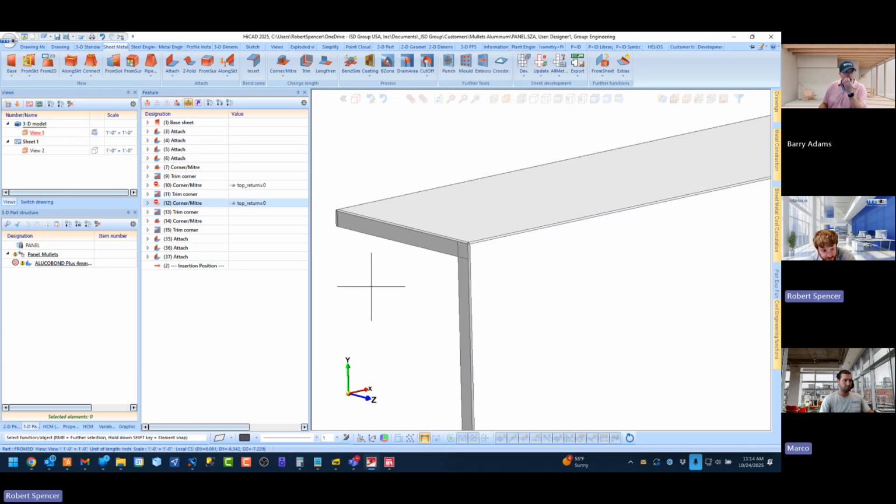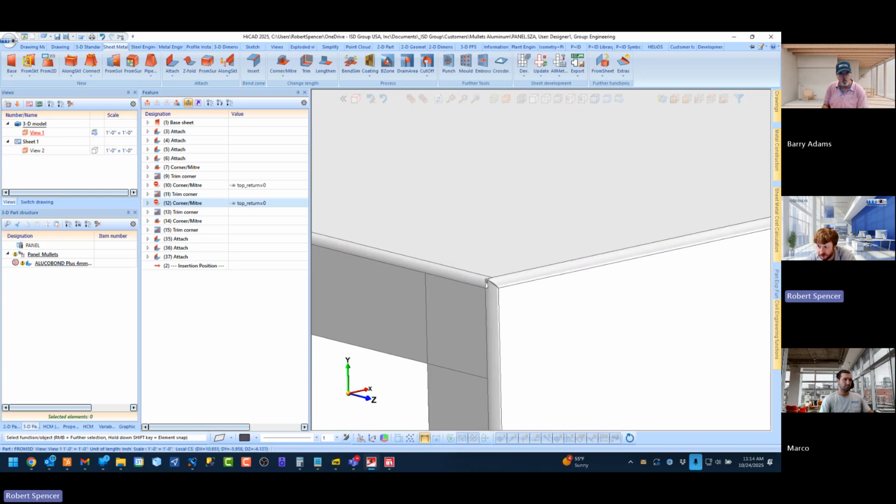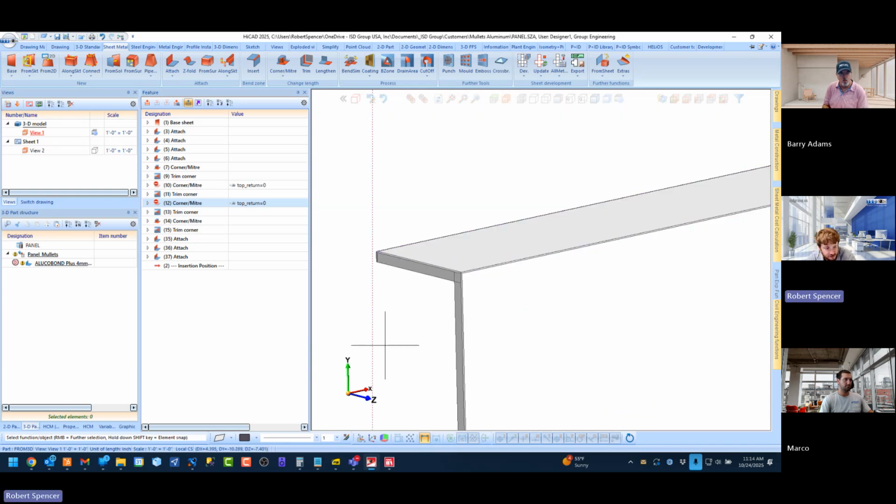When you're selecting planes for parametrics, sometimes it requires you to further define 3 points to give it the plane, because depending on the situation when you need that plane, sometimes lines move based on other variables, things switch on or off, and suddenly an element, say a line or a point, is now not available that you were originally thinking would be available when you built that parameter.